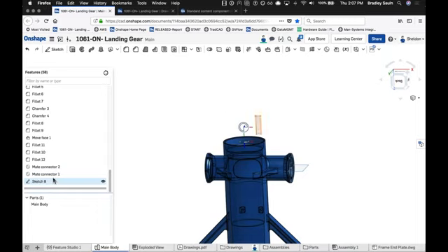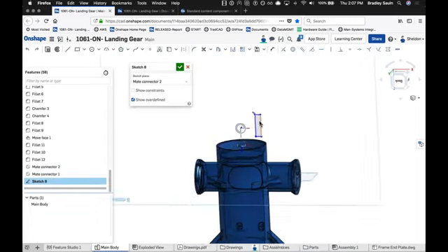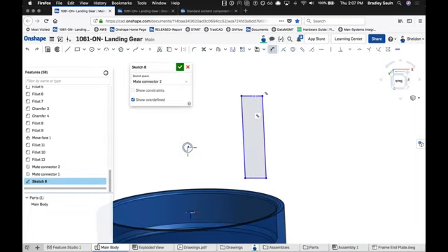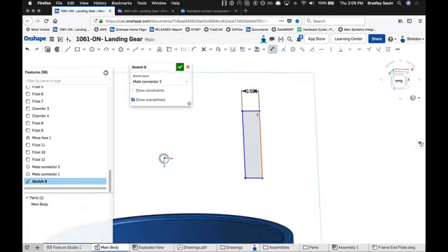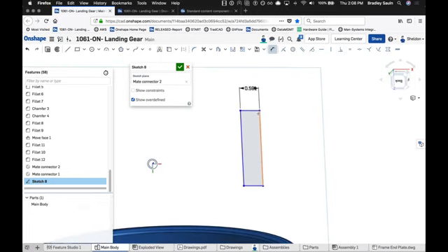Now if I go back into this sketch really quick, and we just do a quick dimension of this, and let's make this, let's say 15 millimeters. This is a pretty small relative sketch component, and maybe I did want to add a sketch fillet to these edges. In the past, we could always click and drag to place a sketch fillet, but it wasn't always discoverable.